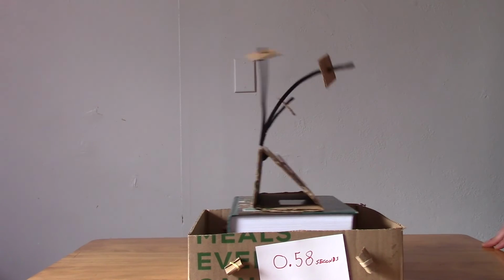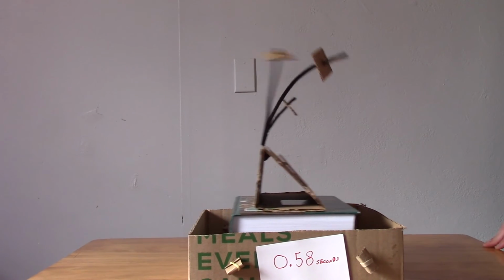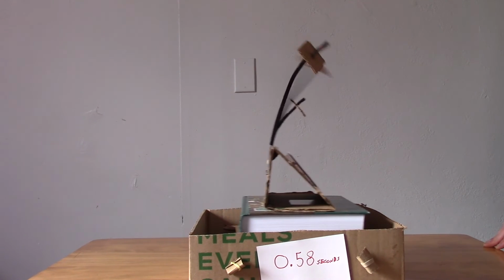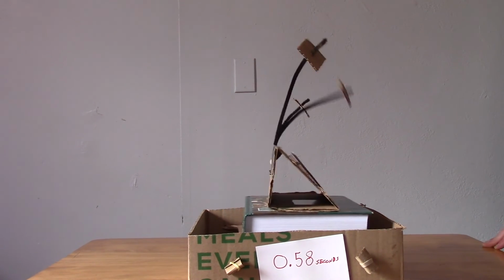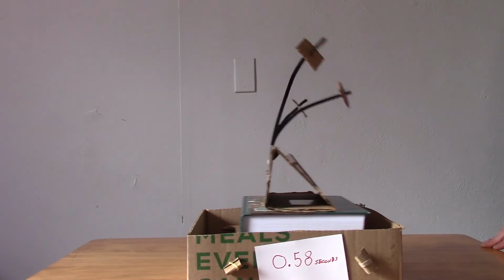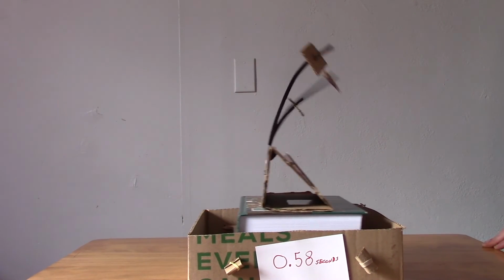Remember that the period of the ground motion is determined mostly by the type of soil that the structure rests on. For this reason, engineers must predict the frequency of the soil based on soil properties and then design a structure that will either not resonate with the earthquake or that will be able to resist very large forces in the case that it does resonate.